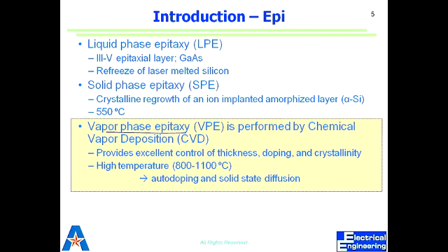There's SPE, where we ion implant the layer and we let it grow at high temperature. So it sort of melts it and regrows. It may not be melting in a solution like where you have a totally liquid, but it would be a surface where the high energy will result in the movement of atoms where they find their place in the lattice. And then there's vapor phase epitaxy, which is the most commonly done, where it's just like CVD.